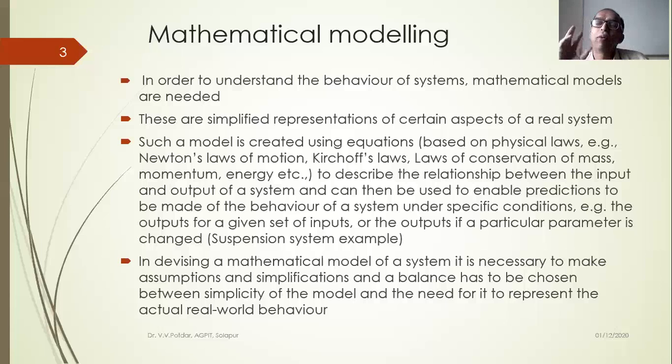Isn't it? What are we using this suspension control system for? For a comfortable ride. So by using these input conditions, I'll be able to predict how much will be the motion transmitted, how much will be the force transmitted to the rider. And accordingly, I'll modify the stiffness. If the displacement transmitted is more, I'll modify the spring design. I'll change the stiffness value K. I'll change the damping coefficient value of a damper. I'll change the fluid so that the damping factor will be different.